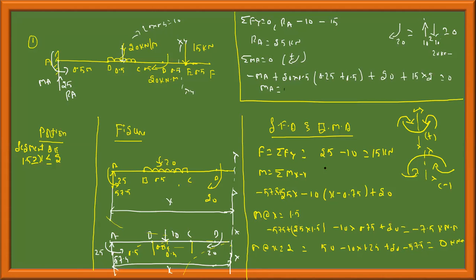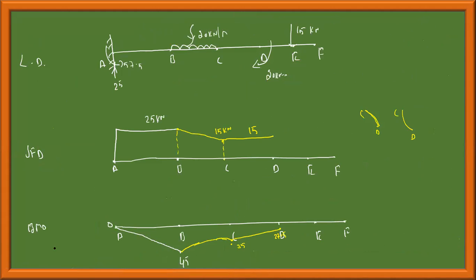The shear force is some 15 kilonewton. Now the force remains the same, 15 kilonewton, throughout the portion from 1.5 to 2 length. I will indicate this: this is 1.5, and each division is 0.5. Throughout 1.5 to 2 it is 15 kilonewton like this.